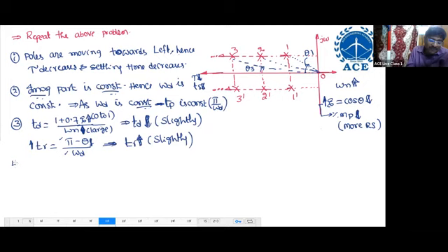Next, fourth one. Peak time, delay time, and rise time are completed. Then next, zeta increases, so percentage of MP decreases. The system becomes more relatively stable. That's all. So the imaginary part of the pole gives the peak time, and the real part of the pole decides the settling time. These two factors we can fix. Okay.